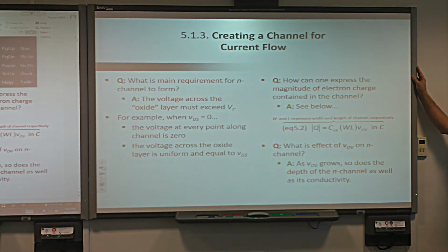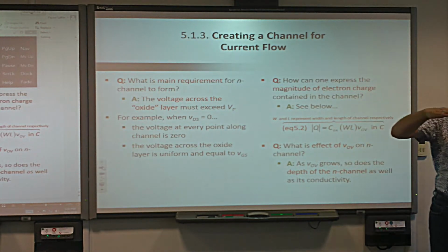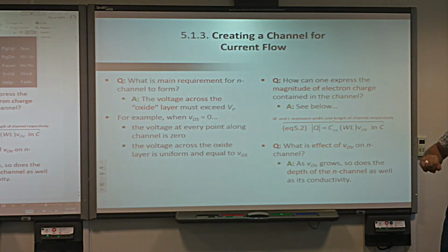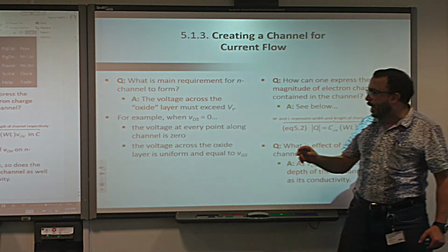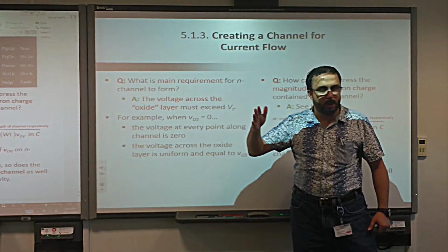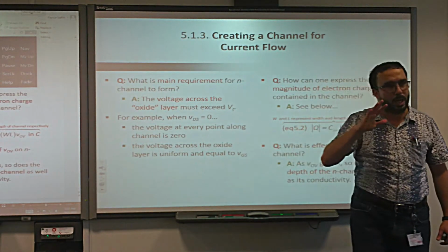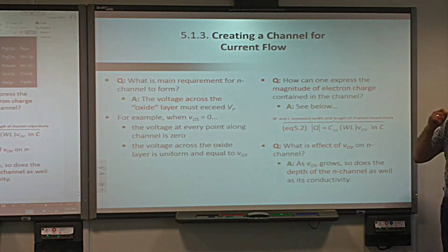If it is a diode, it's exponential, we know how to do that, or other models. Here also it's the same story. How to do that? The first step is to estimate how much charge we have in the channel, for small values of VDS, between 0 and a certain value, which we'll discuss later.